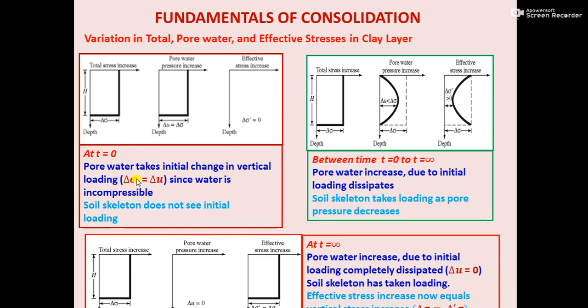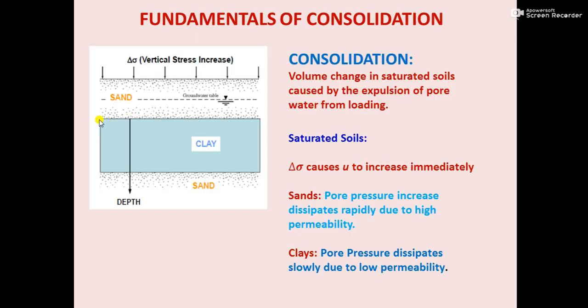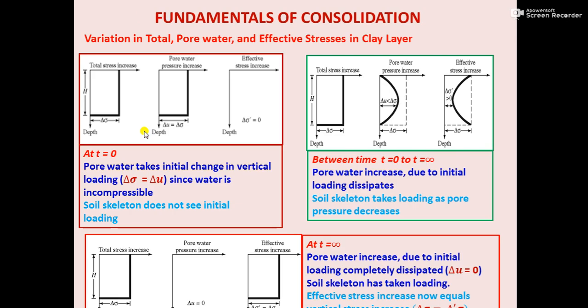That means delta sigma equals delta u, since water is incompressible. Now at this time, if you observe, the soil skeleton does not see any loading. Which soil skeleton will not see any loading? This clayey portion of the soil will not see any initial loading. Why? Because the full incremental load is now being taken up by the pore water. This is the first stage of consolidation.